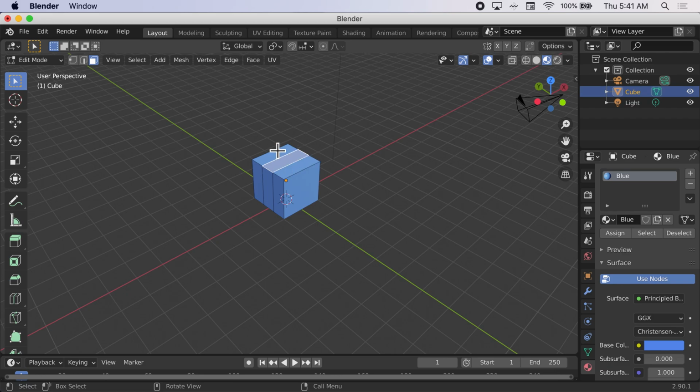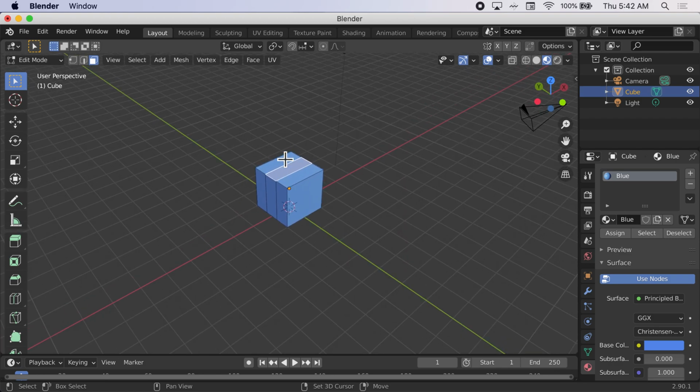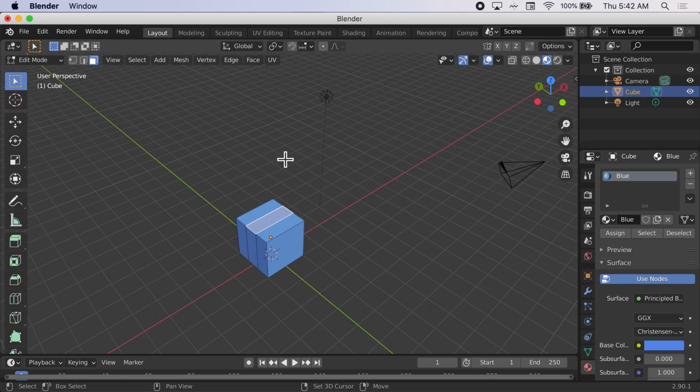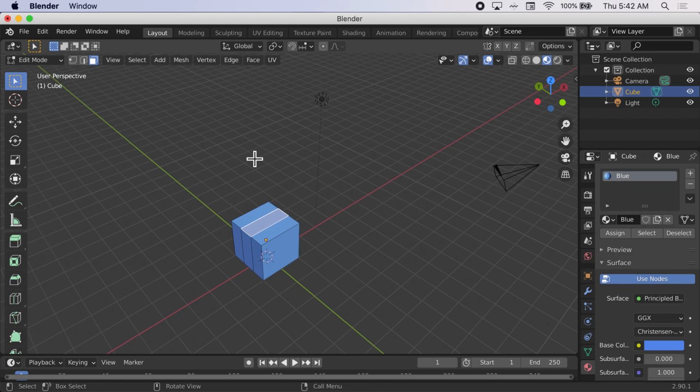It's all those flat surfaces that are on the object. So I'm going to select this particular flat surface right here. I'm going to hold the Shift key down. I'm going to move the camera, pan the camera down a little bit. Right? Already using some of those tools. Now we're going to extrude.